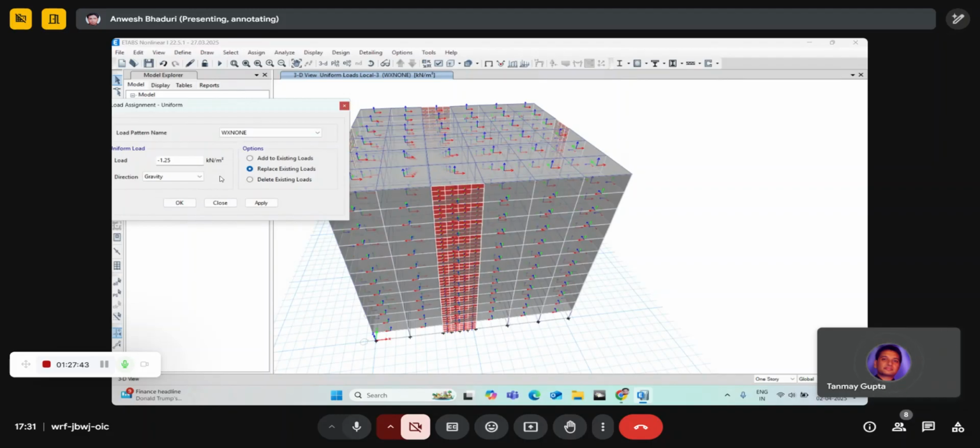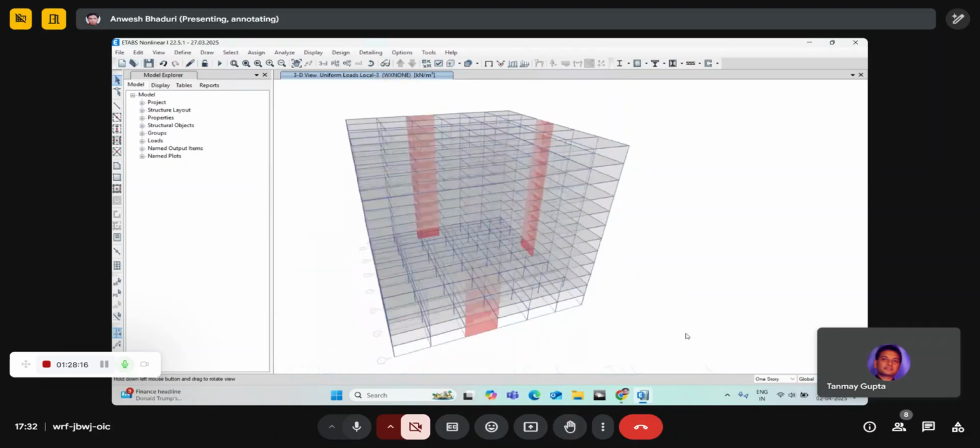Third was the gust factor analysis using the user load manual from the auto lateral loads, and the fourth is selecting the none option from the auto lateral loads and defining it externally. Your wind load combinations for design can be defined manually, or you can always use the automatic load combinations for your design.